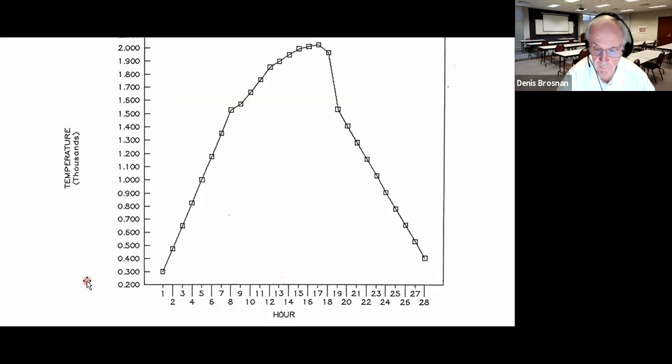Here's a typical firing curve for heavy clay products. You've noticed that we heat pretty fast. Okay, so here's the temperature versus the hours of firing. We heat pretty fast, but we slowed down a little bit here when we got into the area of dehydroxylation. And that's to avoid what are called preheat cracks.